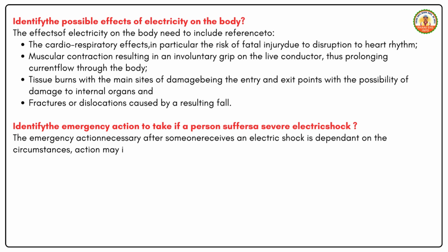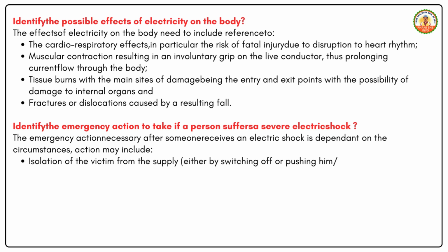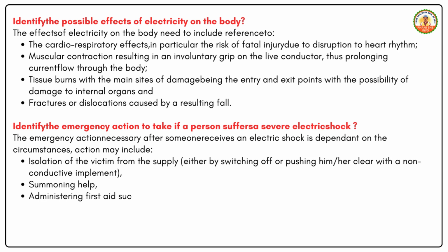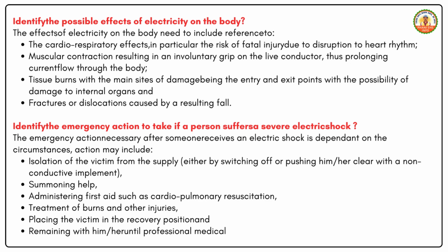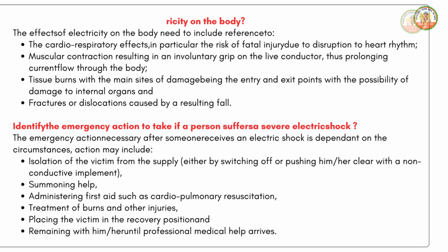Action may include isolation of the victim from the supply, either by switching off or pushing him/her clear with a non-conductive implement. Summoning help. Administering first aid such as cardiopulmonary resuscitation. Treatment of burns and other injuries. Placing the victim in the recovery position and remaining with him/her until professional medical help arrives.